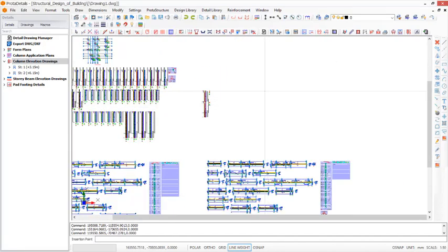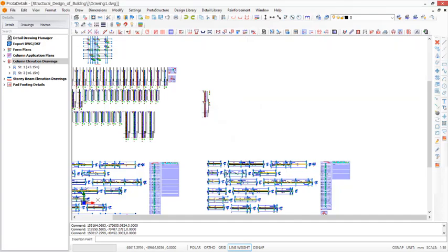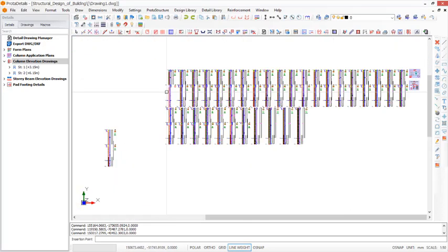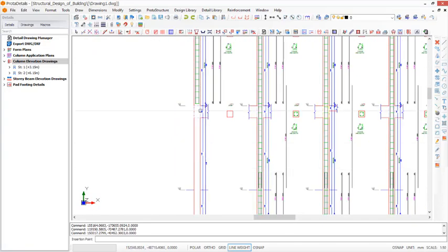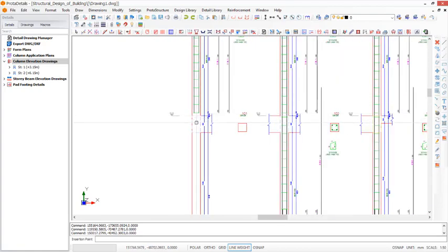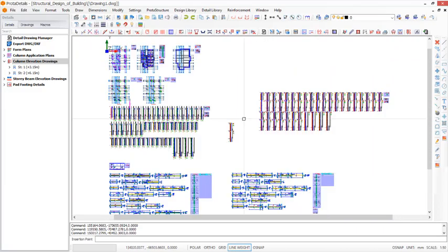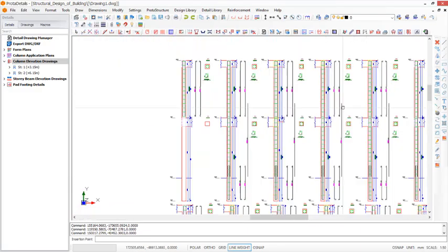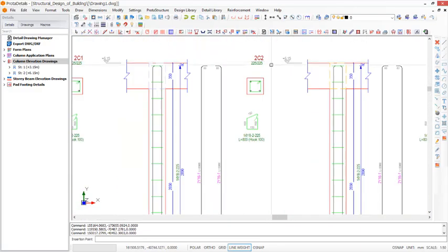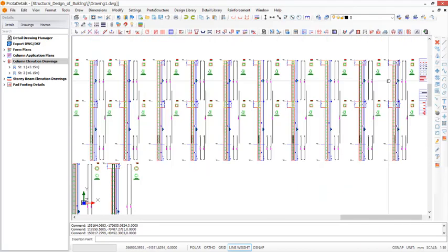So this is going to draw for us all of these columns, but it's going to be through the stories, and then it will give us as well the bar bending schedule. So you can see the way this is being drawn successfully. These columns, you see under it there is no column because this is just like a column resting on the beam. So you can see how it's being drawn successfully, automatically. So check this, and now check this. You now see the difference between if this goes through stories as well as the sections. This is easy and it will make your editing experience great.